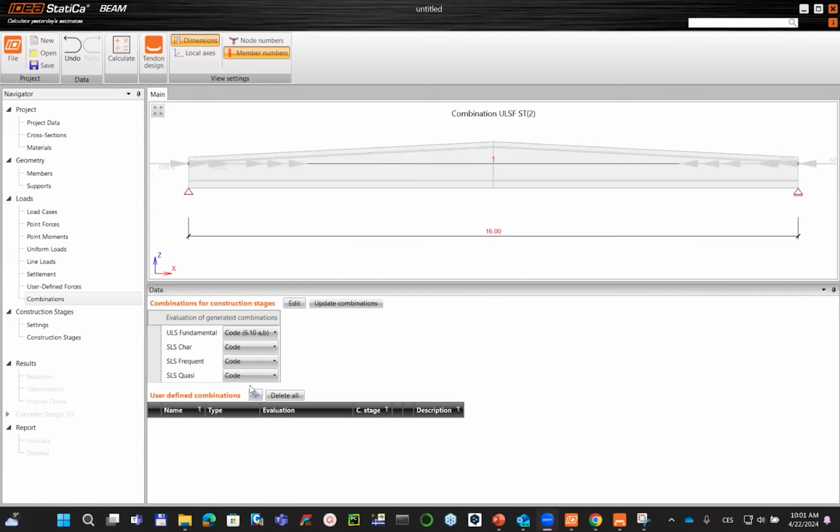If you would like to set a different debonding area, you need to create different sets. In every set, you will apply the debonding length to the group. So if in the group there will be 4 tendons, all 4 tendons will have the same debonding length. So you need to create, let's say, more groups. If you would like to have, in one layer, 4 different debonding lengths, you need to create 4 groups.